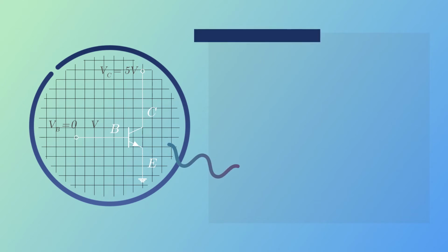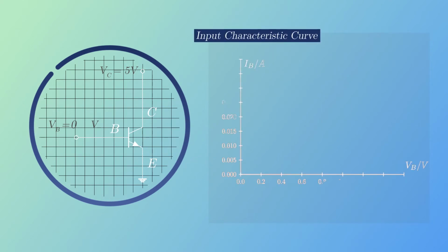Moving up a level, we can depict its behavior at different conditions by plotting its response for some given parameters. Looking at the model, we can see that we have a few knobs we can turn to test its response. The first one being the base-emitter voltage. Ideally, we would like to know how this base current varies with VBE, because the only way that we can turn on this BJT is to have some sort of base current. So by mapping out the equivalent voltage for any base current, it'll expand our framework so that we can work with voltages as well. Let's take a look at how VBE relates to IB.